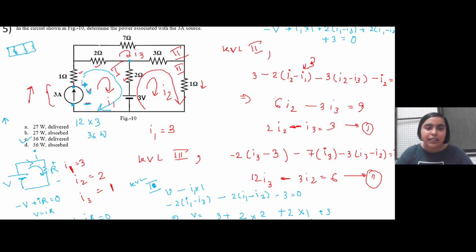If there are multiple resistances connected across this particular resistance, then it is easier to use mesh currents and compute the mesh currents and solve the problem. In both ways you will be able to solve it. Using only KCL you will be able to solve it, using only KVL you will be able to solve it, but how much time it requires to solve it, that is important.